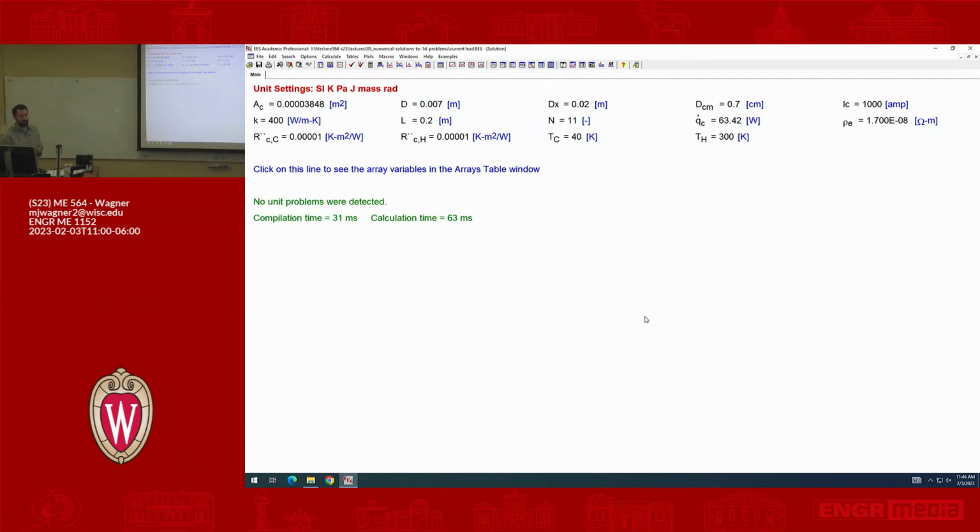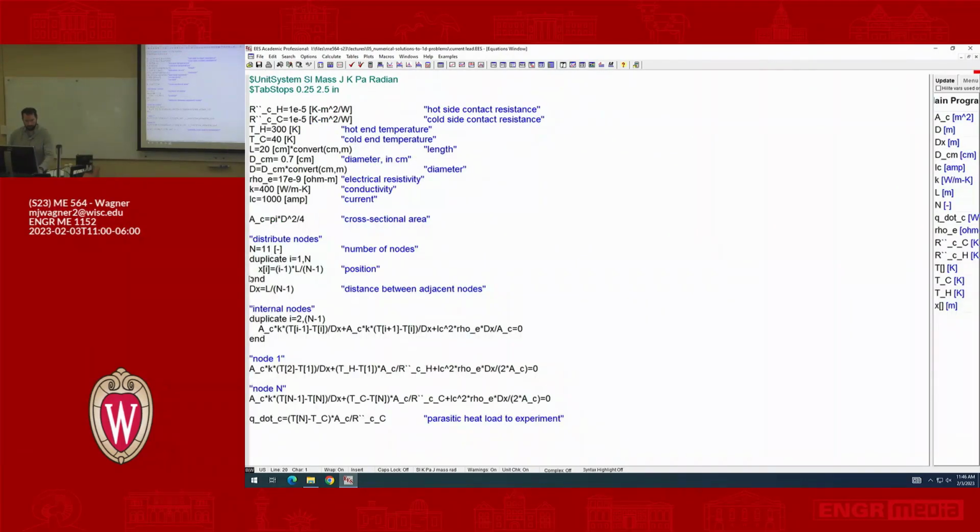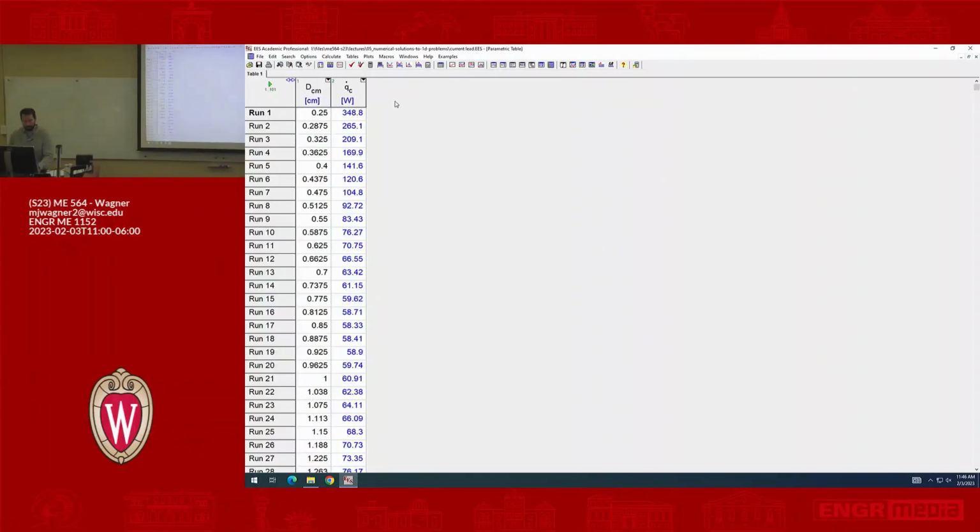There's maybe 2 ways that you would do this. One would be, let's go back here to the equations window. I'm saying here, this is the diameter of my wire. Let's go and create a parametric table. I've already done that. And I'm going to enter some values that I have available. So I know I can buy from McMaster-Carr, whatever, all these different diameters. So I'm going to enter that in and run the table. I've commented it out. It should work.